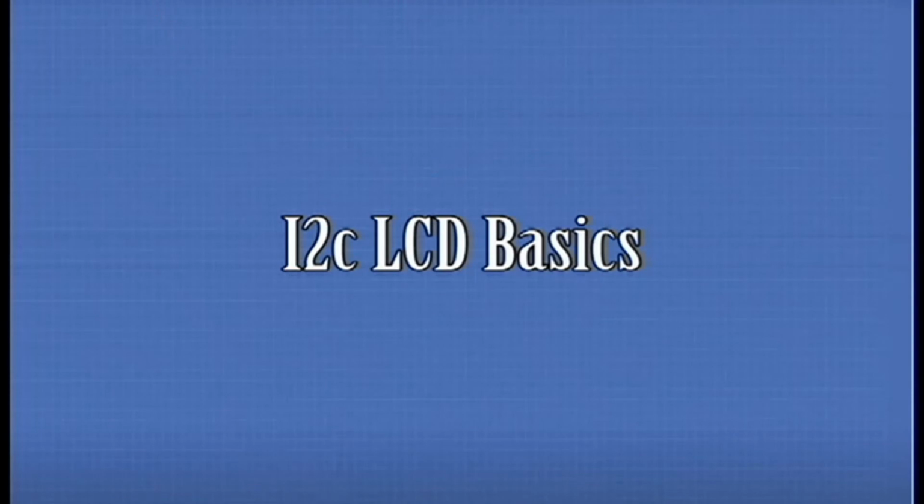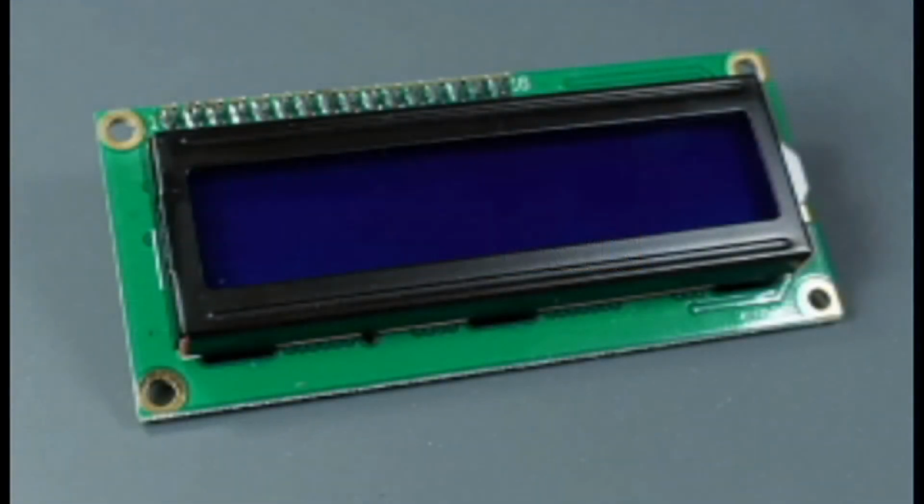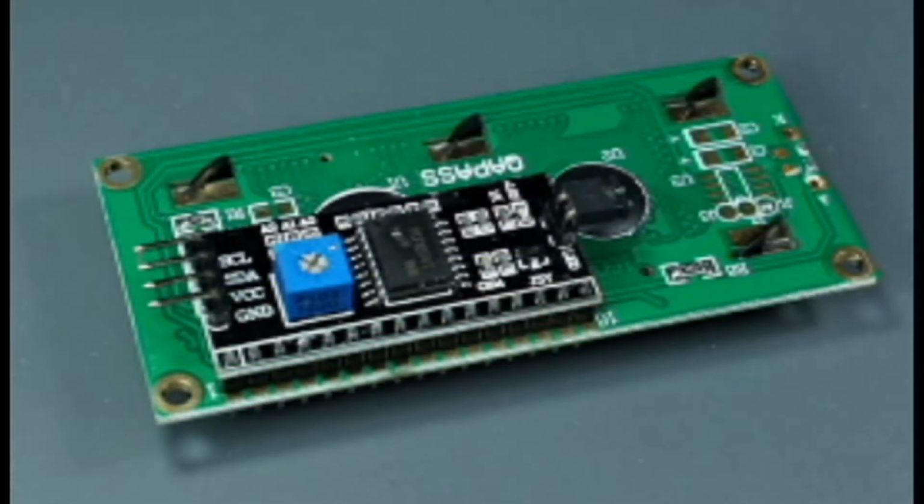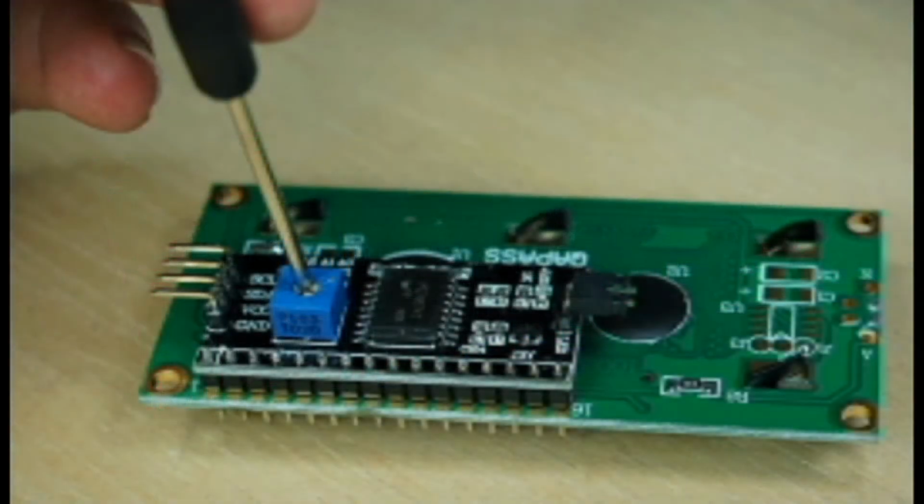I2C LCD Basics. This type of LCD is ideal for displaying text and numbers, hence the name, Character LCD. The I2C LCD that we are using in this project comes with a small add-on circuit mounted on the back of the module. This module features a PCF8574 chip, for I2C communication, and a potentiometer to adjust the LCD backlight or contrast. The advantage of an I2C LCD is that the wiring is very simple. You only need 2 data pins to control the LCD.